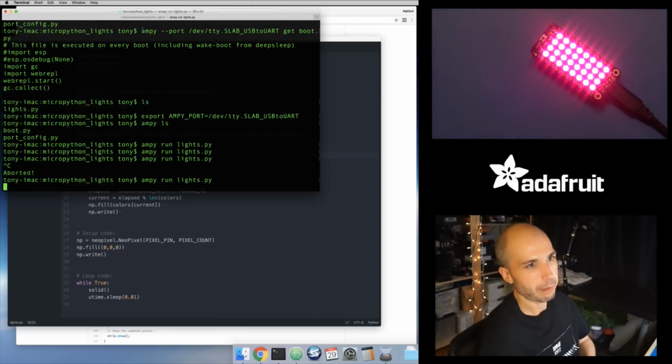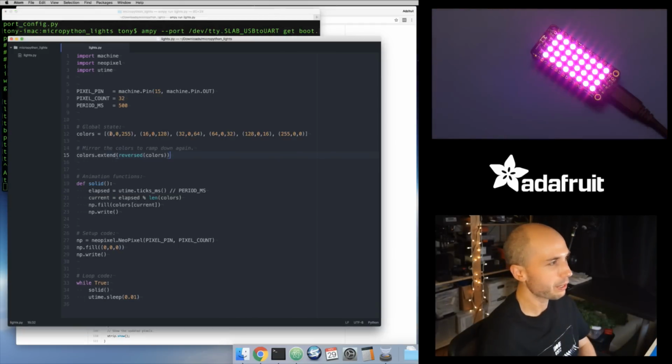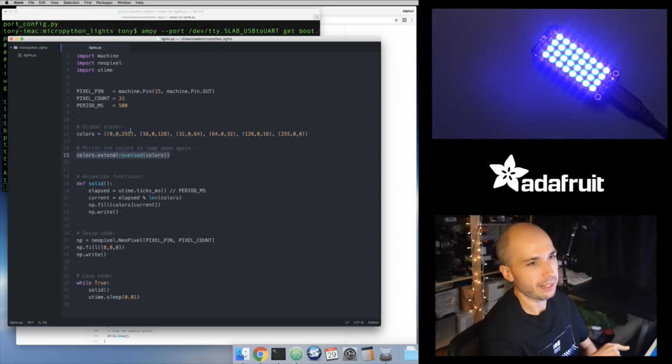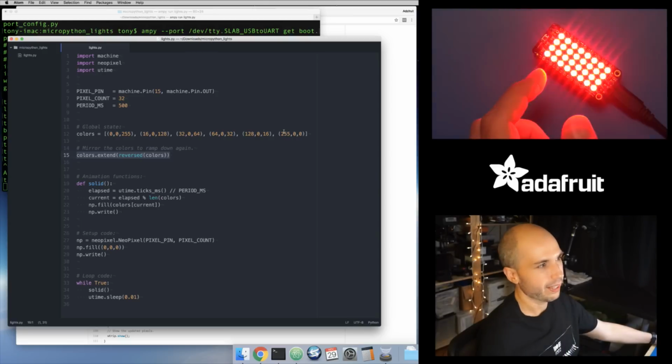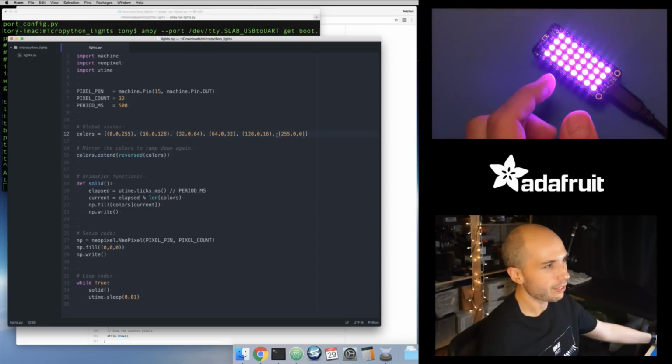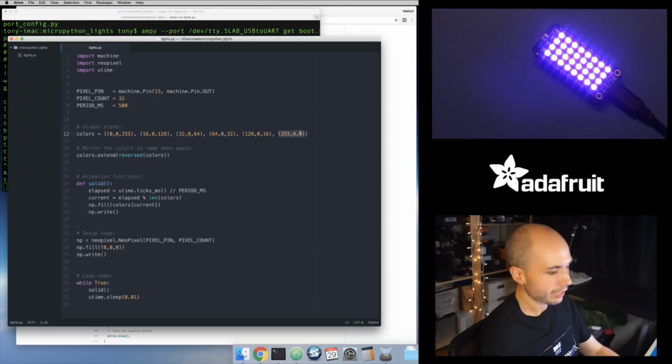So that's cool because, notice I only defined this ramp of colors from blue up to red. This line right here is actually copying that and flipping it so that now it ramps up and down smoothly. But you do notice when it gets that blue color, it stays there twice. That's because when it copies this and reverses it, you get that red color at the end twice.